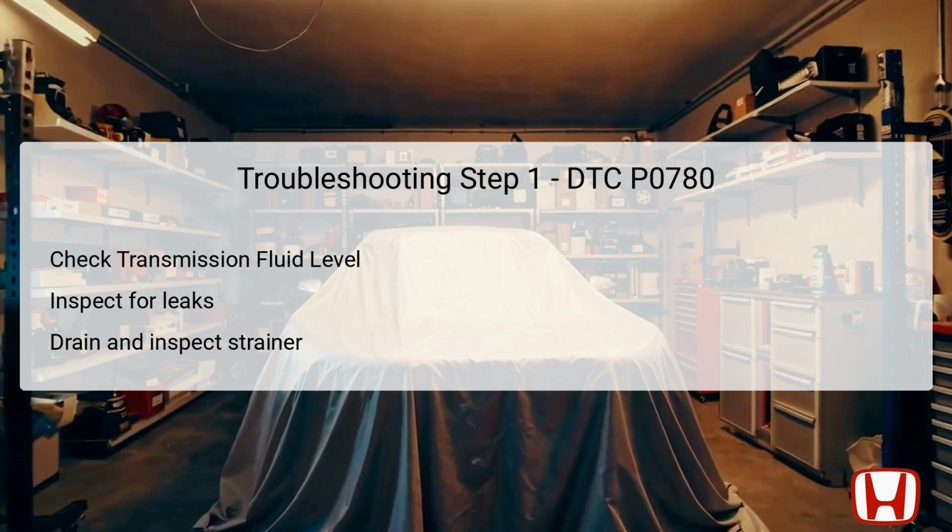Next, drain the transmission fluid using the strainer. This step is crucial as it allows for an inspection of the strainer for any metal debris or excessive clutch material that could indicate internal wear or failure.